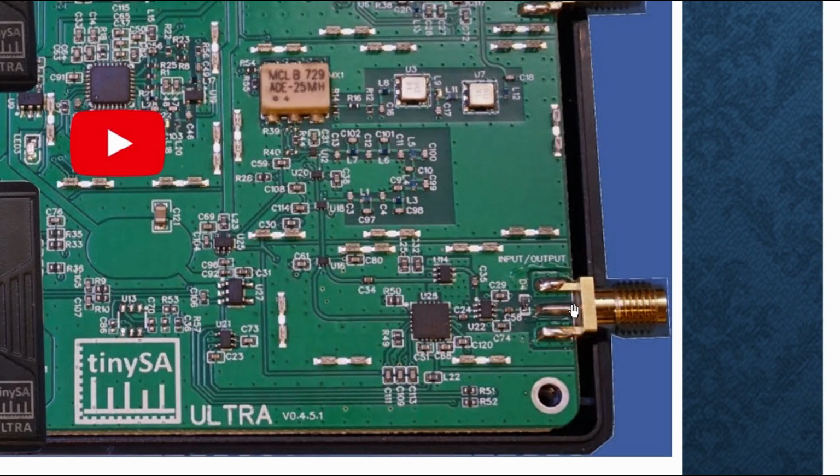This is the RF input connector. The signal comes in, there's a blocking cap, and then there's this electronic switch that routes the signal either through this path or through this path. The lower path has the attenuator, like a 0 to 30 something dB attenuator chip. But if you want the LNA, then you have to switch to the upper path, and this is the low noise amplifier chip. Then it goes on either this route or this route into a low pass filter, and then into a mixer that up converts it, in the case of the lower band 0 to 850 megahertz, to, I don't know what these filters are, probably 915 megahertz or something. They're soft filters that provide the very strong channel selectivity.